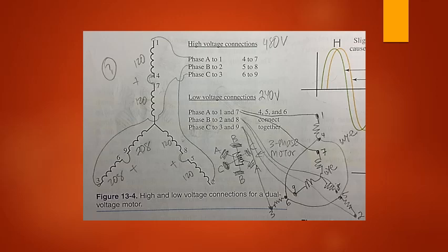The motor is started and then brought up to near synchronous speed. The speed of the motor can be varied by adjusting the rheostat in the control circuit outside of the motor housing. This allows the current induced in the rotor windings to be varied. By varying the currents through the rotor circuit, the speed of the rotor can be adjusted. Although a full range of speeds cannot be accomplished this way, a great deal of variation in speed can be achieved.